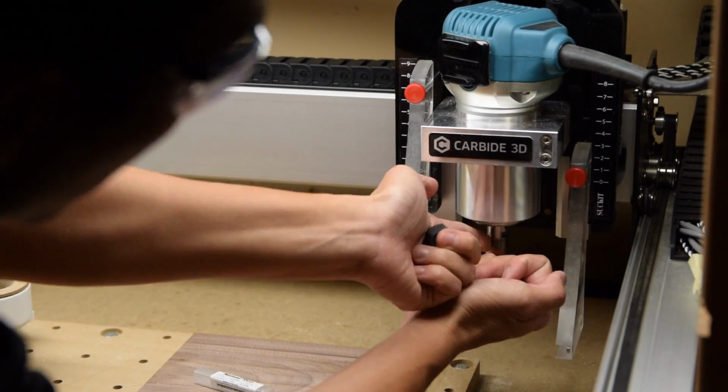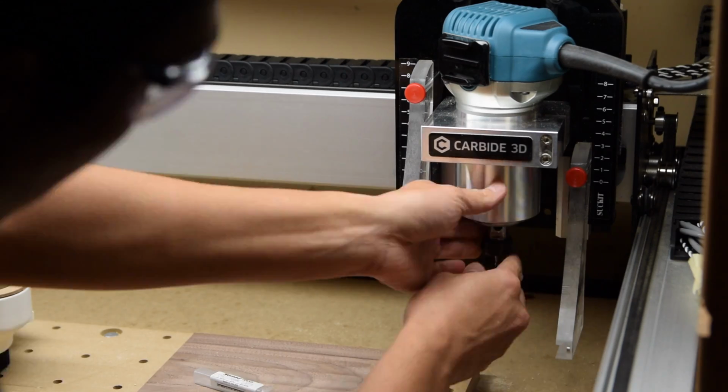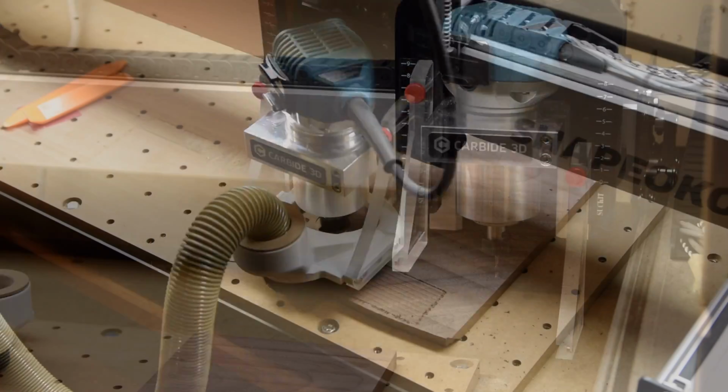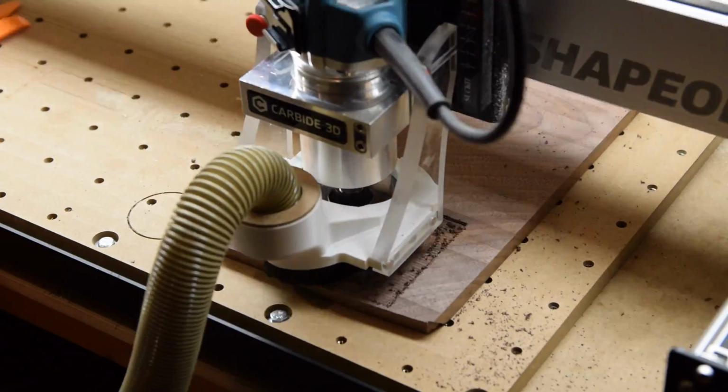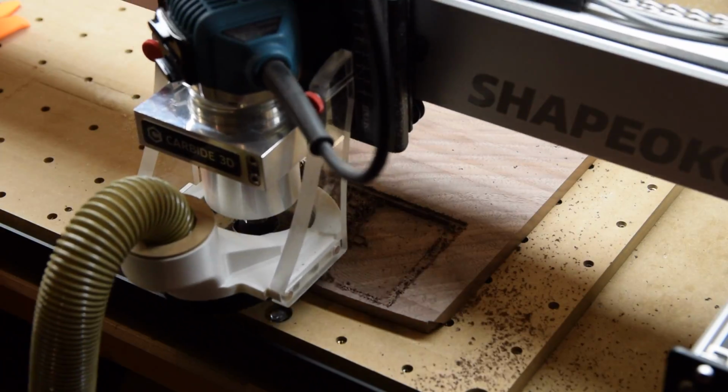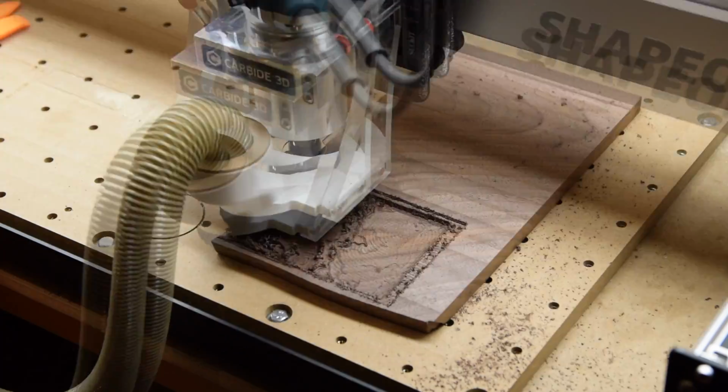With the tape strategically positioned under where I wanted to cut out my part, I could go straight into my toolpaths. Face, adaptive, contour, tool change, parallel. Really straightforward. It was about an hour to run all of these, with the majority of that in the parallel toolpath.